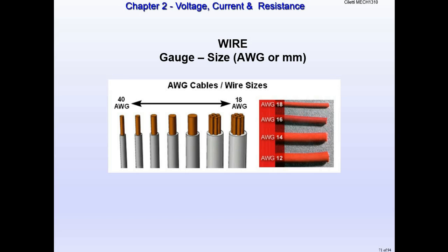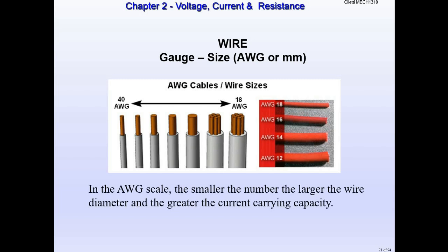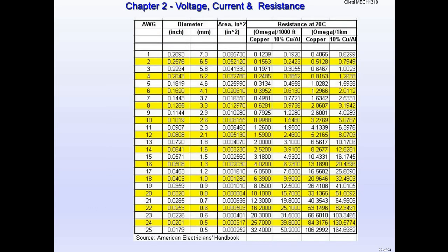Okay, because if you use too small of a wire, it's going to burn up and melt and cause a fire. That's essentially it's for safety. All right, can you use a really small wire to draw big current? Oh, absolutely, for maybe a couple seconds until it blows up. All right, that small wire just becomes like a fuse to that large current, and it'll just blow right up.